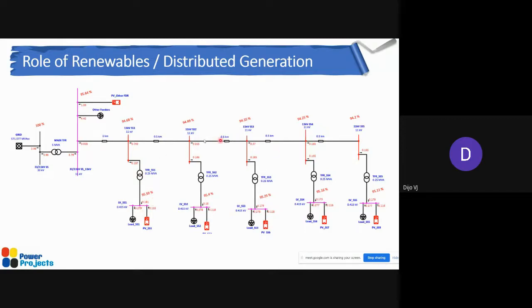So now you can see here when the solar is added, it's very close to 95 percent. Probably if you add some capacitor banks or something at the load centers, you can maintain the voltage well within this 95%. So the solution is simpler there.